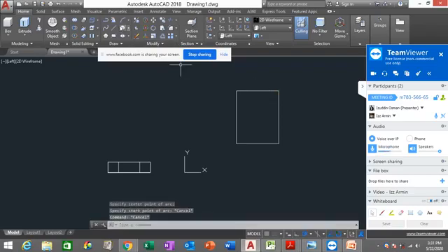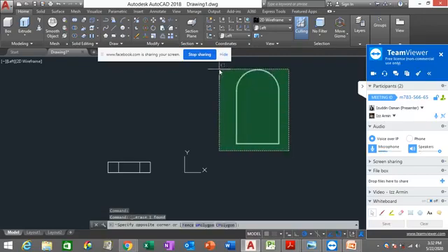Sorry. So when you click arc, right? The AutoCAD command will ask you to specify start point or center. All right. So I'm going to specify the center. So I'm going to type C, enter. Specify center point here. Put the start point here. Click and click. All right. So I'm going to select this and delete it. So this is my 2D profile for my left view.